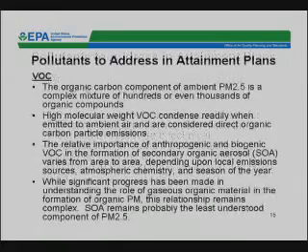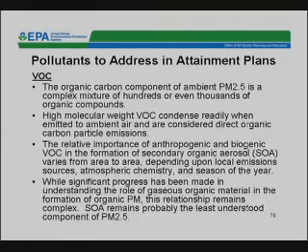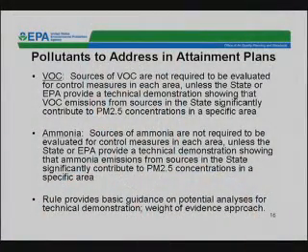In terms of VOCs, the organic carbon component of ambient PM 2.5 is a complex mixture of hundreds or even thousands of organic compounds. High molecular weight VOCs condense readily when emitted into the ambient air and are considered direct organic carbon particles. Other VOCs react in the atmosphere to form secondary organic aerosols. While there's been significant progress made in understanding the role of gaseous organic formation of organic PM, this relationship remains very complex. And for this reason, the policy is the reverse of the policy for NOx, which is that sources of VOC are not required to be evaluated for control measures in each area unless the state or EPA provide a technical demonstration showing that VOC emissions significantly contribute to PM concentrations in a specific area.